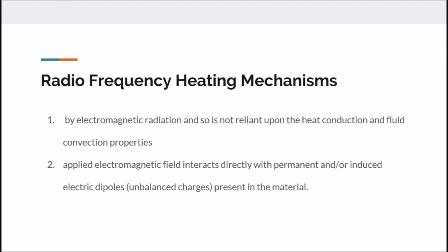This is due to the fact that radio frequency heating heats materials quickly and efficiently because all the heat transfer occurs at a molecular level instead. The applied electromagnetic field interacts directly with the permanent and/or induced electric dipoles, and the dipoles are just an unbalanced charge, which happens to be present in the materials.